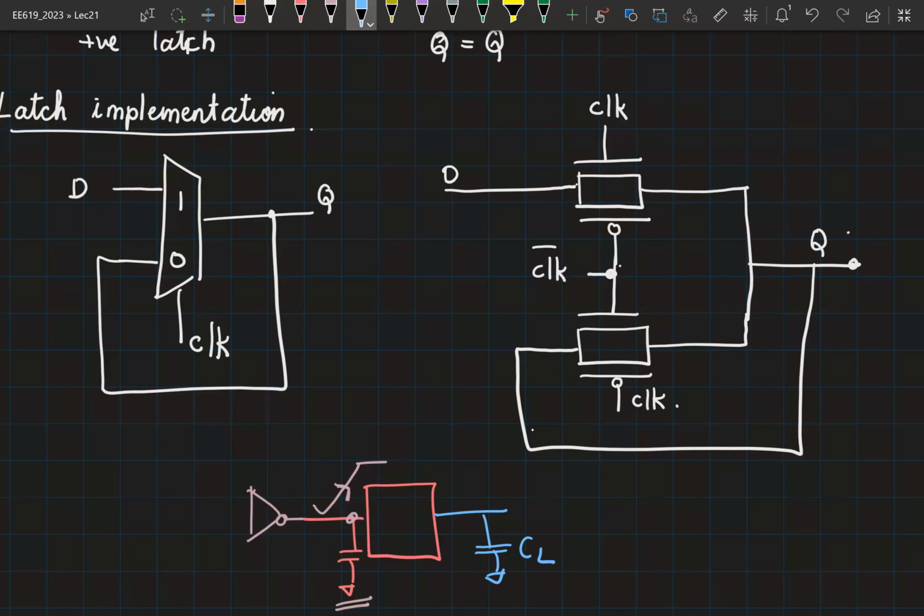So you will have a 2D table with one side being the rise and fall time information, the other side being the capacitance. And now for any combination of rise time and load capacitance, you can either pick the value directly from the table, or you can interpolate two values and estimate the delay that you expect. So all those calculations you cannot do for this circuit, because the drive strength information is not included with it. So every time you use the circuit, you'll have to see what is driving it, how much load is there, and then estimate the full delay.